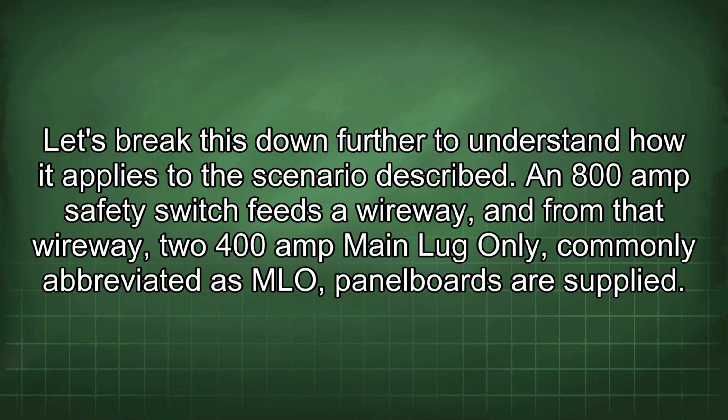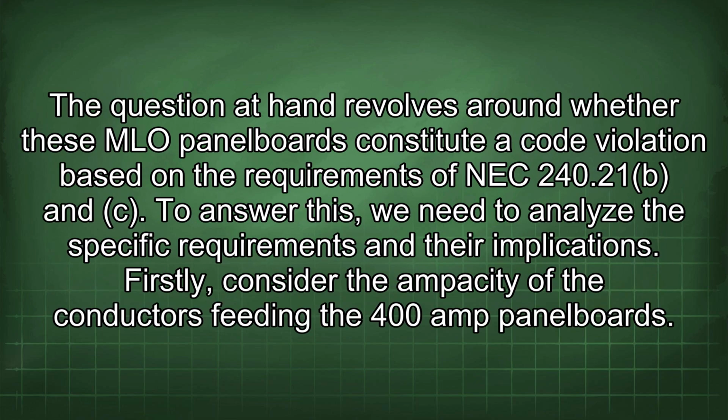An 800 amp safety switch feeds a wireway, and from that wireway, two 400 amp main lug only, commonly abbreviated as MLO, panelboards are supplied. The question at hand revolves around whether these MLO panelboards constitute a code violation based on the requirements of NEC 240.21(B) and (C). To answer this, we need to analyze the specific requirements and their implications.